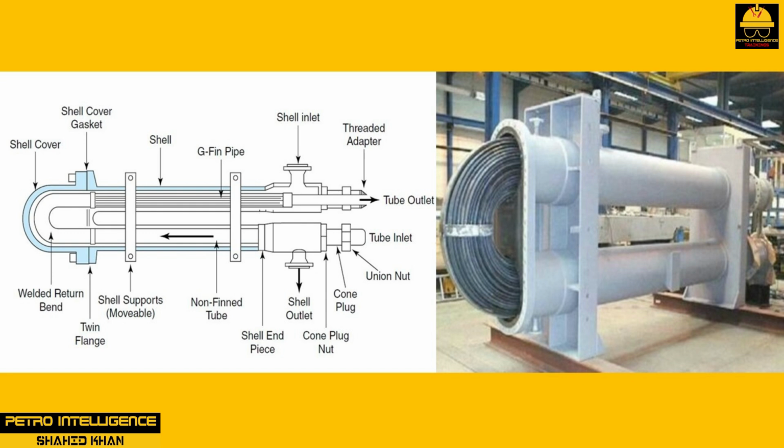The hairpin design has several advantages and disadvantages. Among its advantages are its excellent capacity for thermal expansion because of its U-tube-type shape, its fin design, which works well with fluids that have a low heat transfer coefficient, and its high pressure on the tube side. In addition, it is easy to install and clean, its modular design makes it easy to add new sections, and replacement parts are inexpensive and always in supply. Among its disadvantages are the facts that it is not as cost-effective as most shell and tube exchangers and it requires special gaskets.